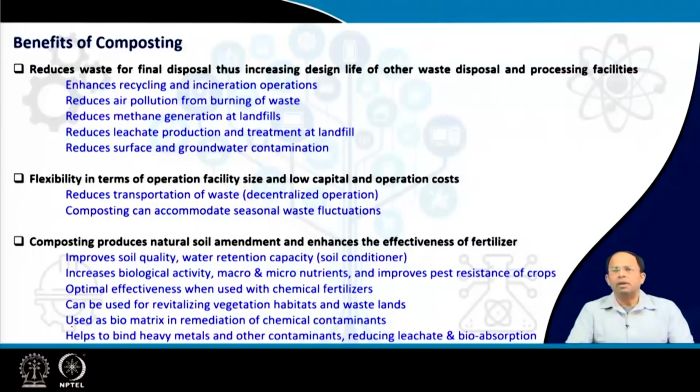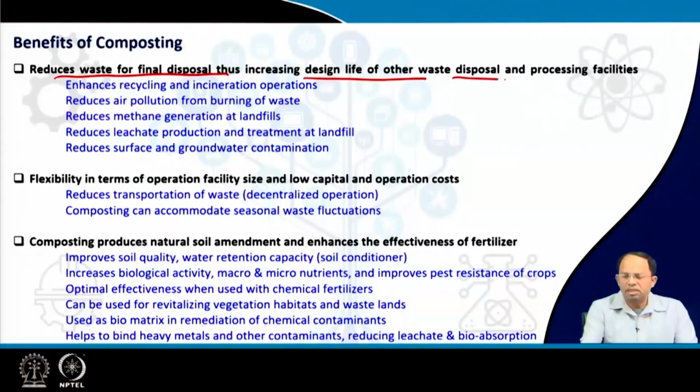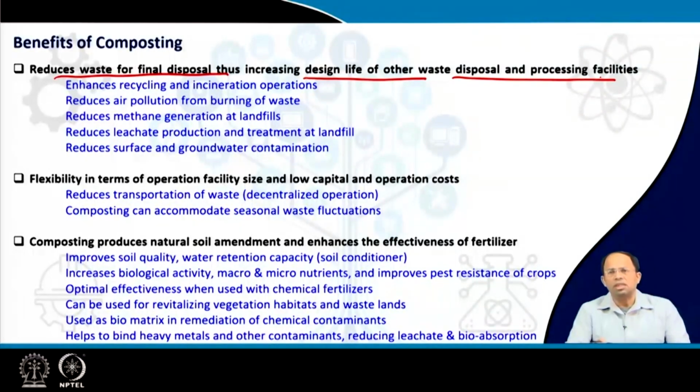Now, what are the benefits of composting? One benefit we already talked about, it's reduction of the transportation cost. But in general, composting reduces waste for final disposal, thus increasing the design life of other waste disposal and processing facilities. Now, it not only increases the design life, it also improves the efficiency of the processes that are taken up in those processing facilities. Processing or disposal facilities could be a landfill site, an incineration plant, where waste is incinerated or converted to energy, or a co-processing plant, or wherever it is.